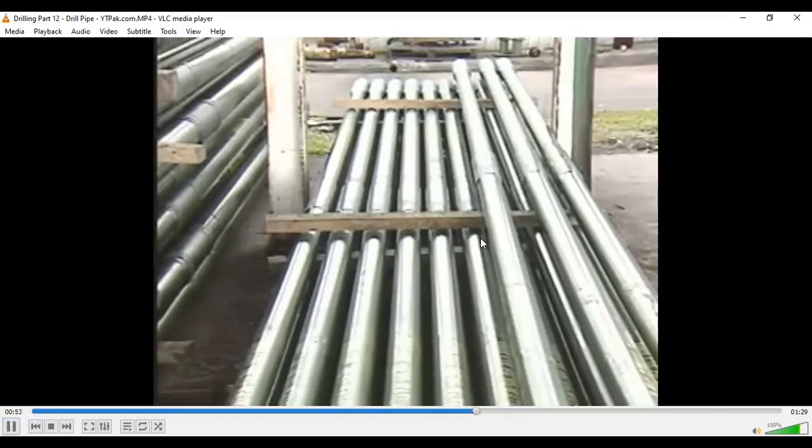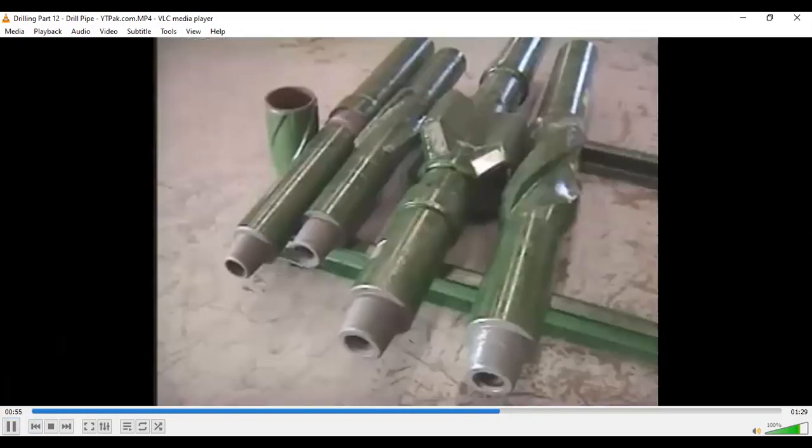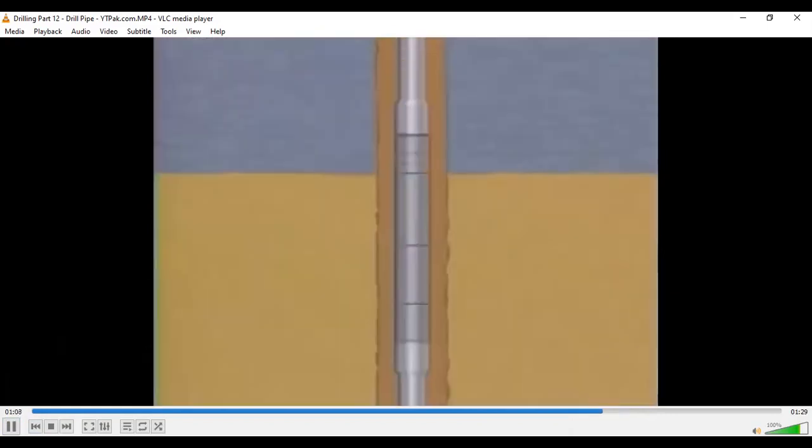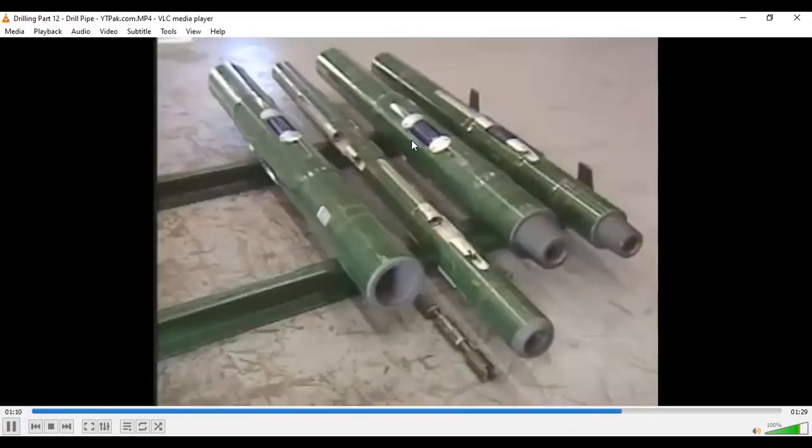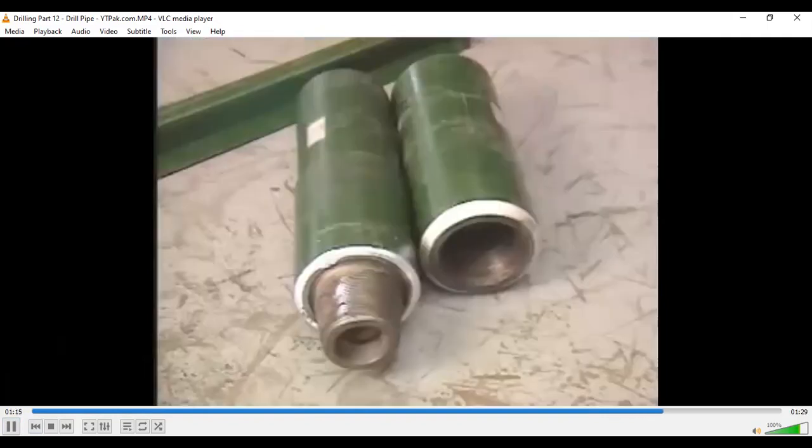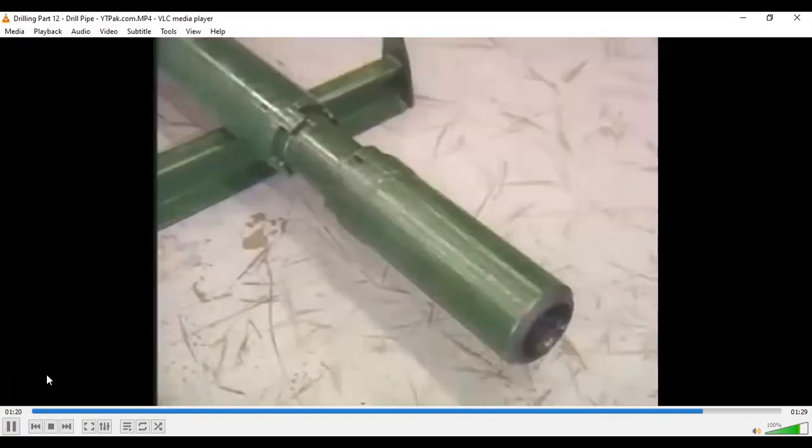It also aids in directional control. Stabilizers help centralize the drill collars, maintain full gauge hole diameter, and depending on their placement in the string, work to drop, build, or maintain hole angle. Jars provide a means of freeing stuck pipe. These are the jars. Rotary reamers prevent bit gauge wear and help ensure a full-size hole diameter. Crossover subs link tools having different types of end connections, and vibration dampeners, when properly applied, absorb vibration and shock loads produced by the bit to keep them from being transmitted up the drill string.